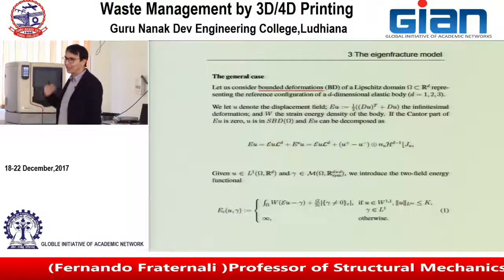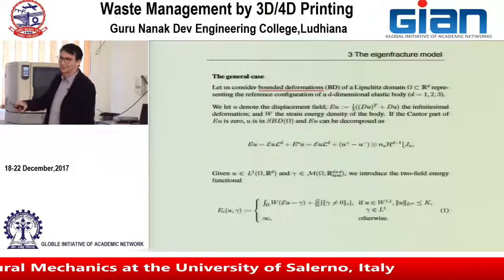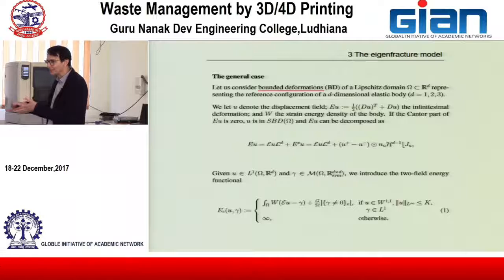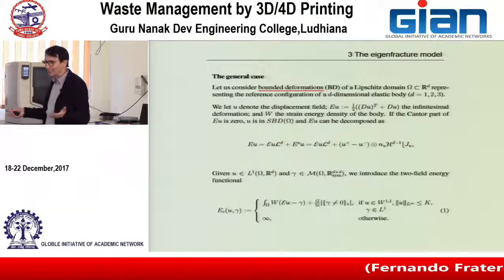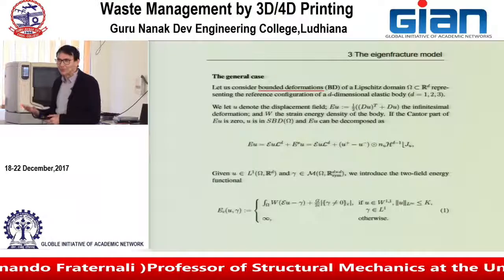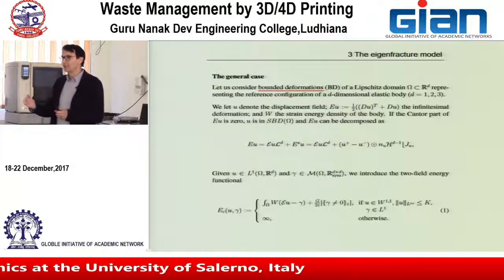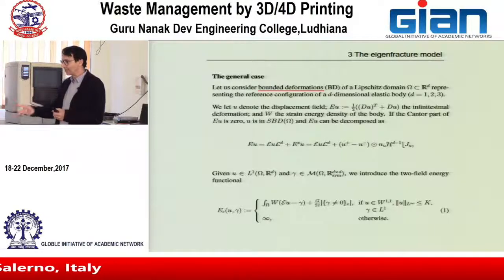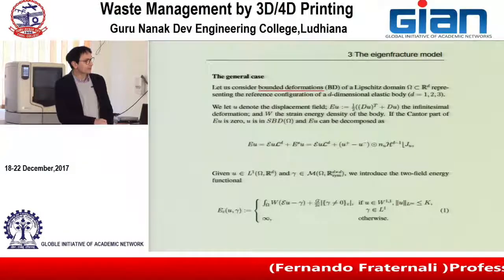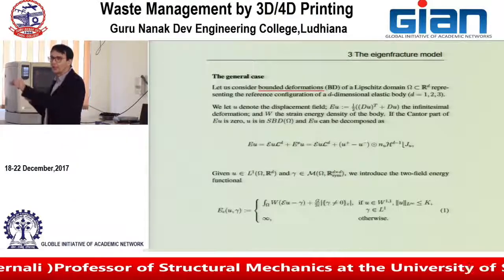Because engineers have tried for many years to do this. What do you do if you want to model a crack? You remove some elements. This has been tried many times. It's not our invention. It's an old story. But it doesn't work if you don't do it properly. So how do you measure the energy that you need to crack an element? Okay, so the measure of gamma different from 0 would be the volume of that element.